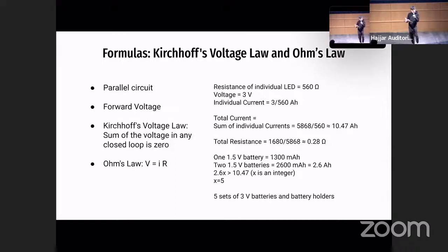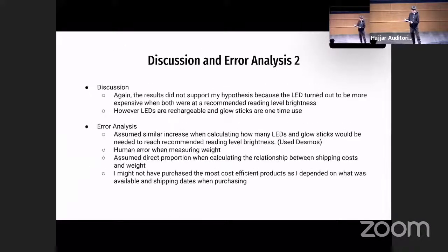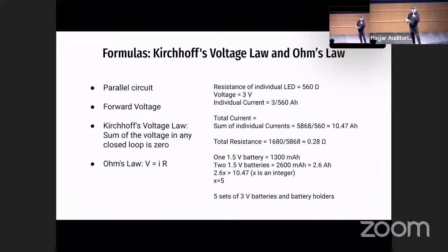It is the amount of voltage you need to get the current to flow across the LED diode. And the voltage across the LED will never be higher than that forward voltage. At the highest supply level of 12 volts, the circuit will draw 20 milliamps, which is the max rating for the LED. And then I'll explain the two laws.